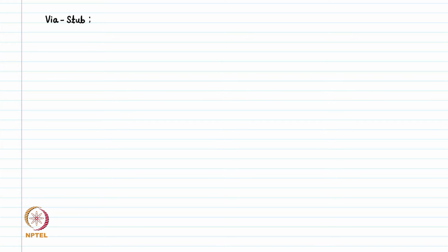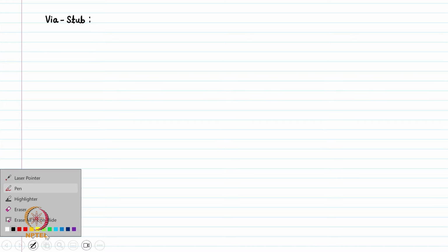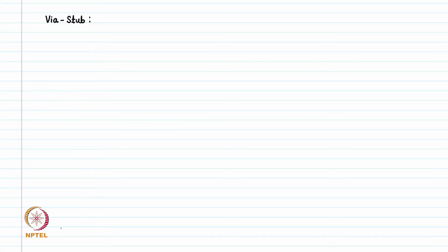So when a routed signal starts from the top layer and ends with some inner layer or the very bottom layer, the remaining portion from the inner layer to the bottom layer is called a via stub.